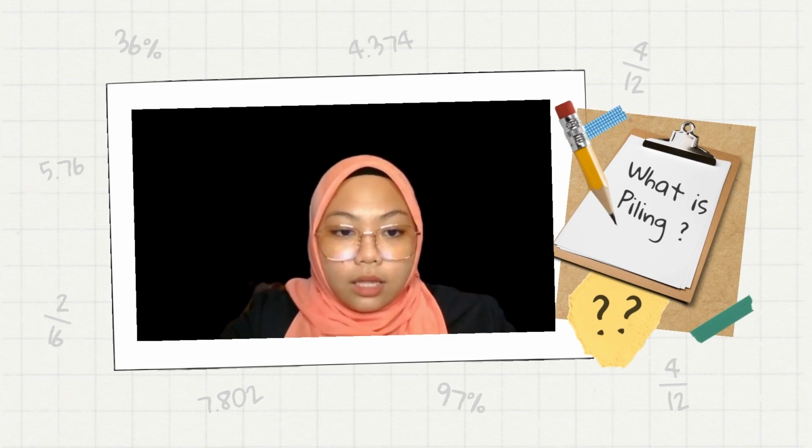End-bearing pile load is supported by resting onto a firm stratum such as bedrock or stratum of subsoil with the required bearing capacity, while friction pile load is supported by the frictional resistance so created between the contact surface of the pile and the embracing soil.